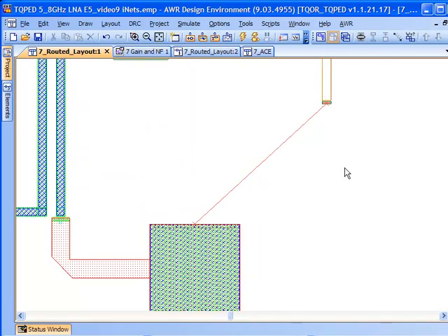Now this resistor is providing some isolation, if you will, from a bond pad that we may want to use for some bias control. In our initial design, we were thinking about 0.5 volt here because these are enhancement mode devices, and this would put the bias on the gate of those devices. Additionally, we may want to go back and redesign this so we can, off the 3.3 volt supply, just step down to 0.5 volt and provide that directly to our circuitry, but have an alternative here that we could go ahead and provide an external bias or bias control if the process shifts a little bit, or if we have some sensitivity to input or output match we didn't anticipate.